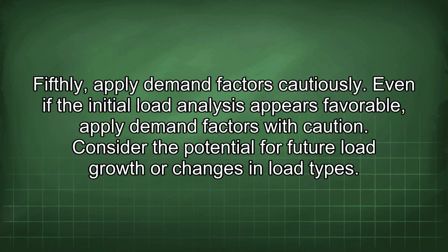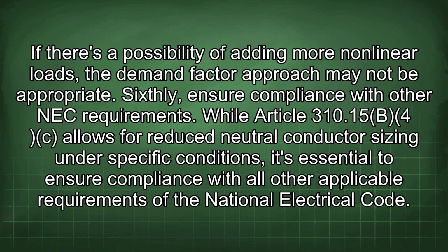Fifthly, apply demand factors cautiously. Even if the initial load analysis appears favorable, apply demand factors with caution. Consider the potential for future load growth or changes in load types. If there's a possibility of adding more nonlinear loads, the demand factor approach may not be appropriate. Sixthly, ensure compliance with other NEC requirements.